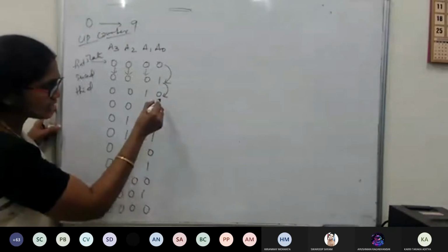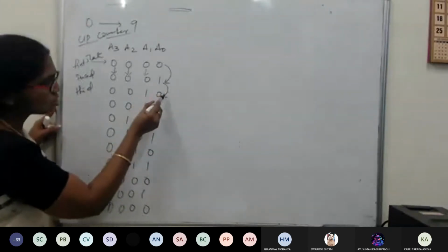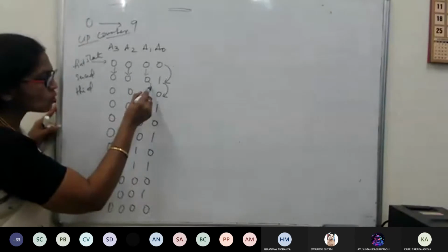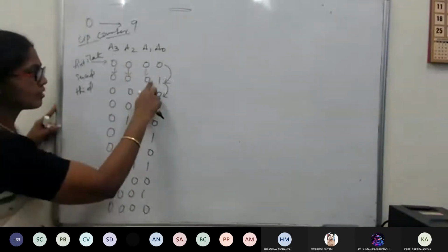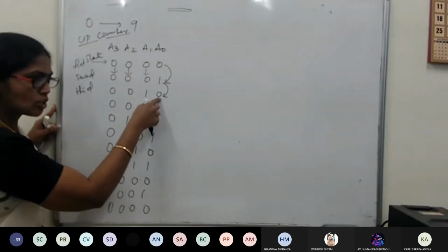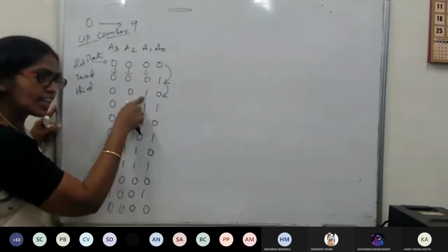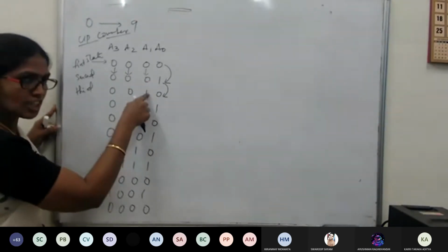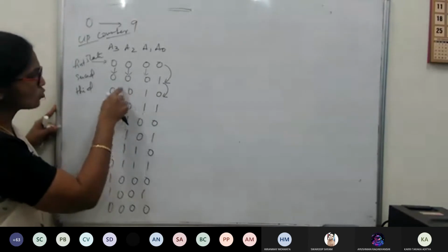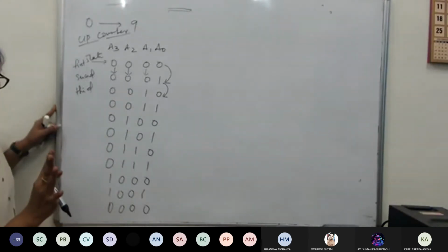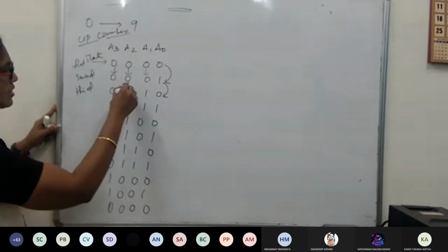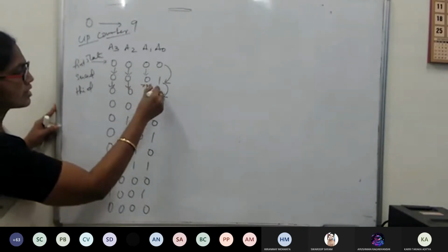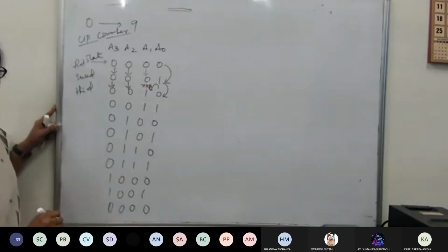From the second to the third state, it has moved from 1 to 0, so immediately there is a change here also. A ripple has come here. That means the 1 to 0 change has created a change in the next bit, where 0 to 1 change has happened. As usual, in the next one nothing has changed, but this one introduced a ripple.